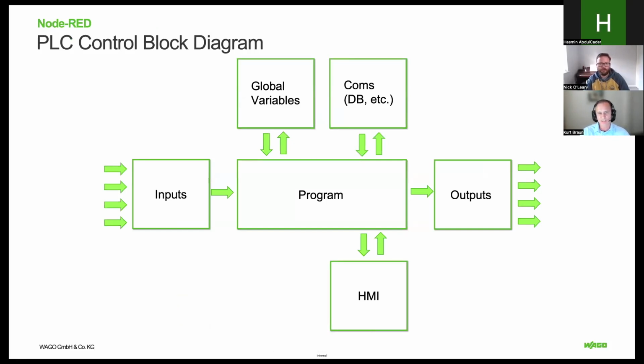If you think about how a PLC operates, you have your physical inputs and outputs. And those are usually handled in your PLC runtime. Then you have all your programs that are running in a task or various tasks. You have global variables that are available to all those programs. You might have communications to different external devices that you need to manage, and then you might have an HMI component for the actual operator interface. So if you keep these concepts in your head when you're looking at adopting this in Node-RED, it helps to try to mimic more or less these functions in your Node-RED instance.